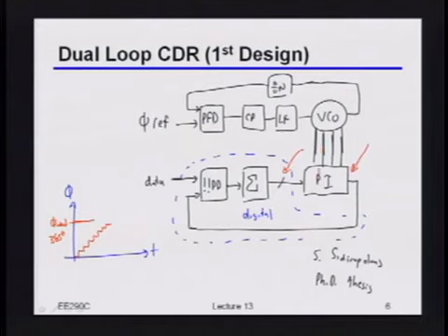Okay? And so with that phase interpolator, I can still have my bang-bang phase detection, again just that up-down signal, pass that through some sort of accumulator, and then use that to figure out the digital control bits that I feed into this phase interpolator. Again, that phase interpolator is what I'm going to be using to clock the actual data. The advantage of this is that this upper loop can be high bandwidth, whereas this lower loop, which is now really the CDR loop itself, I can make very low bandwidth, because I'm taking these relatively clean clocks and just using them to change the actual sampling phase.